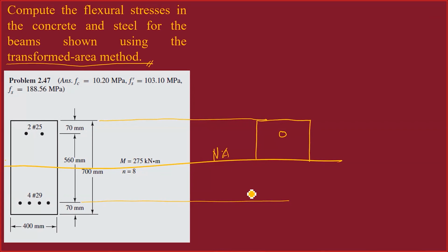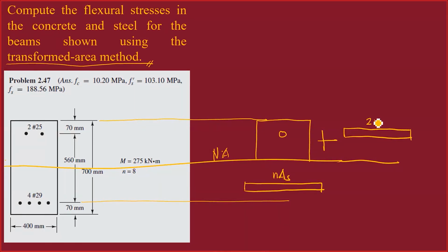Okay? Then here below, the equivalent area of steel in concrete is equal to nAs, right? Of course, it is not a hole that is occupied by steel, but we place it there plus calculate here for the purpose of discussion. Here we have 2n multiplied by As prime. Got it? Here is the concrete in compression.